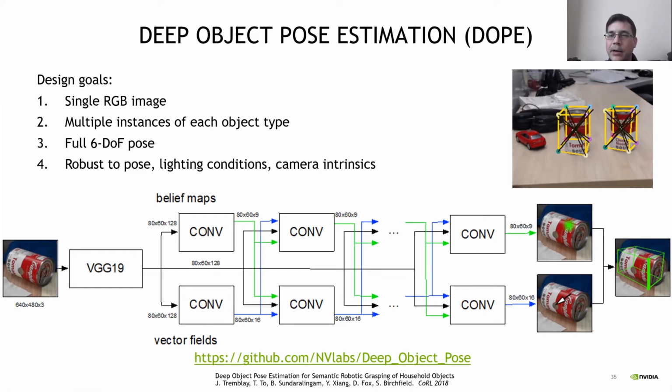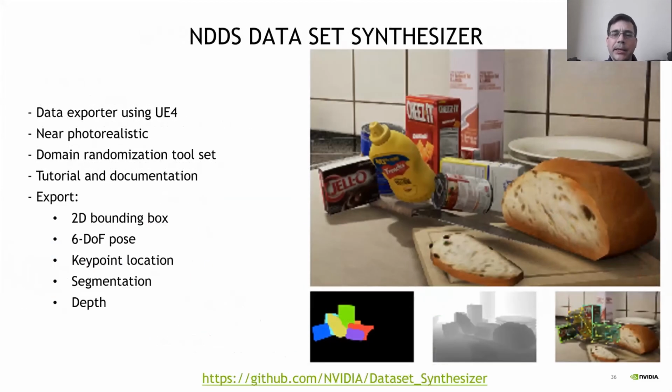So, okay, cool. So then you see that we get this 3D bounding cuboid pose in full 3-dimensional space. And then because we have the camera intrinsics, the network detects everything in 2D on the image plane. And then we use the standard perspective-n-point algorithm, if you're familiar with that. It's just a standard algorithm from classical computer vision to then lift those points from 2D to 3D, given the dimensions of the object itself and the camera intrinsics. And so now we have the object in 3D. We have what's called a 6 degree of freedom pose estimation of that object.